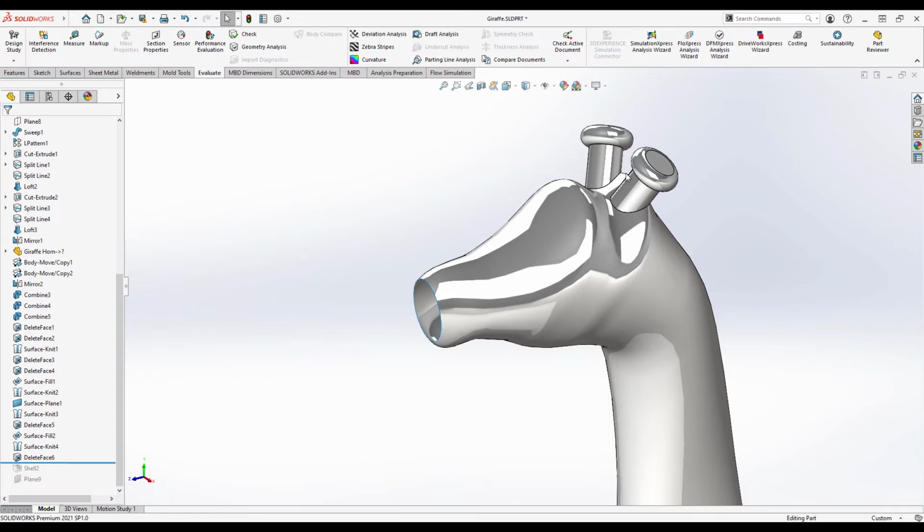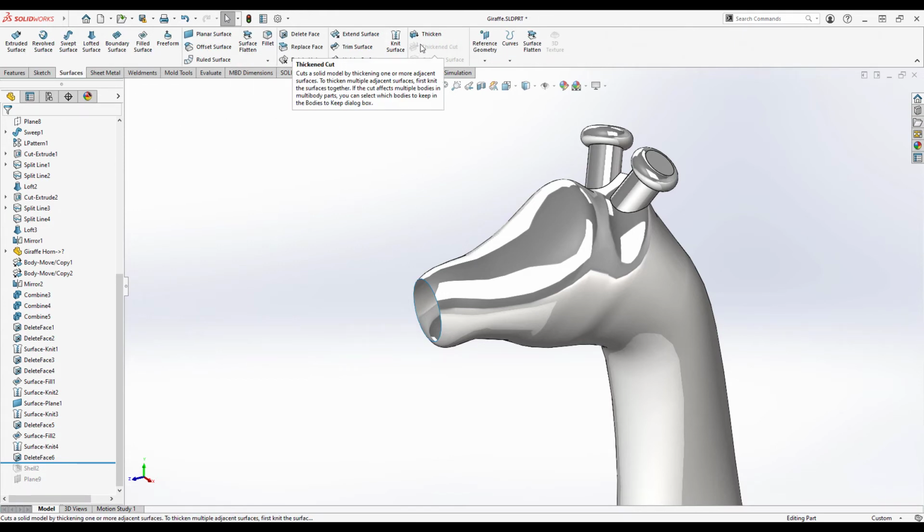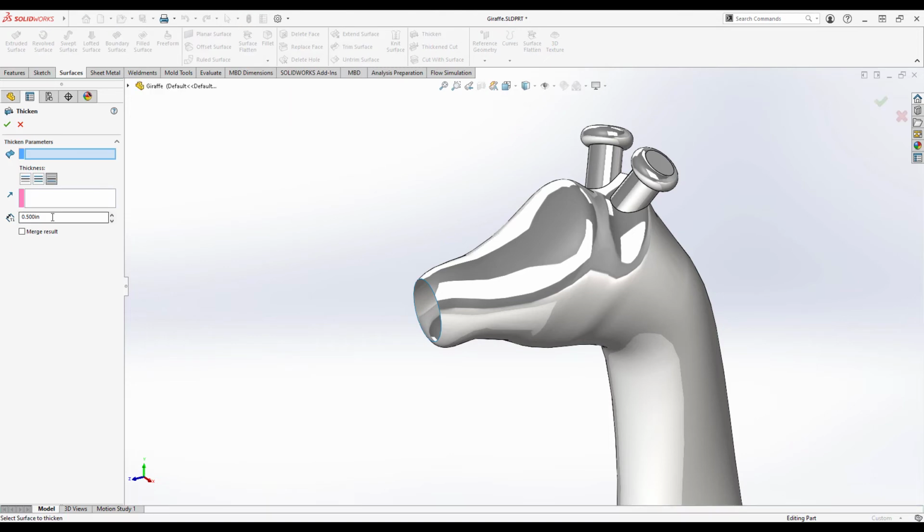I can go in and adjust my splines that determine the shape of this, or I could simply, for the purposes of what I'm doing right now, thicken it to a slightly smaller amount, such as 3/8. And when I click OK to that, now it works without problem.